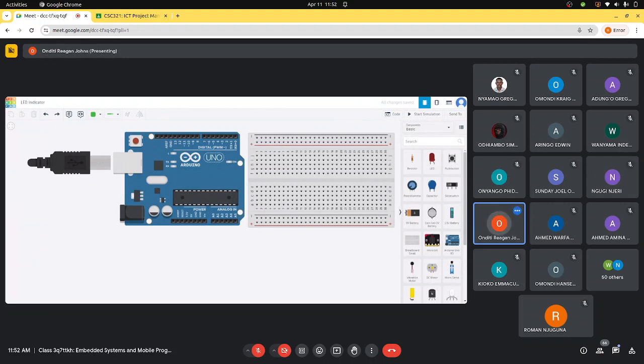So the VIN port down here would be able to give us more voltage into this particular device. So if I do want to have a device that would consume more power and it cannot be supplied using my jack and it cannot be supplied using my USB, then I would use the VIN port to be able to feed in that power. And with the ground here, then I think you'll have enough power that all the components on your circuit would operate without a problem. So fair enough.